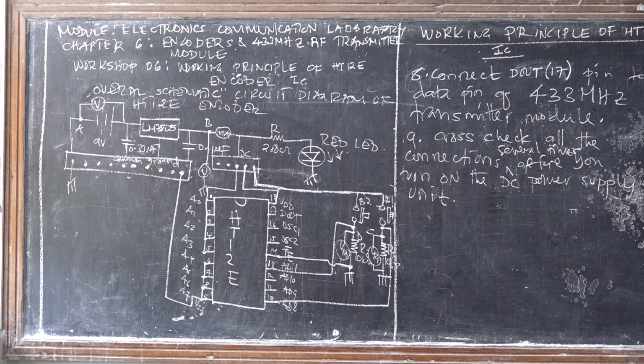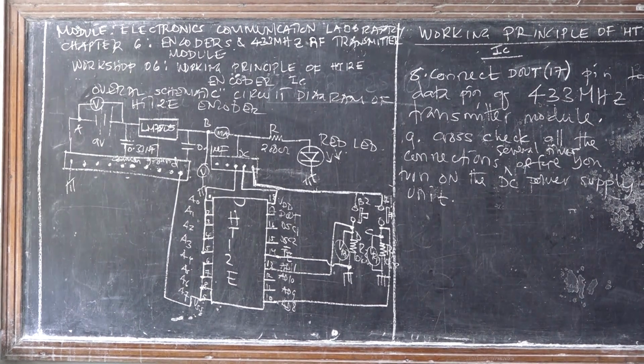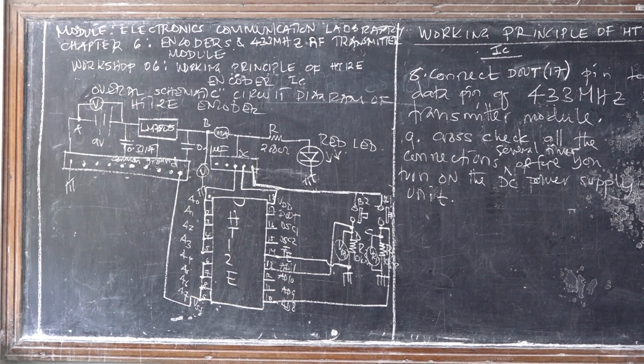The first sentence is just to give you the overview that this HT12E encoder integrated circuit has a built-in oscillator. That built-in oscillator needs an external resistor to trigger it in order to oscillate during the encoding. So to design the oscillator is simple, because you're oscillating always, right?